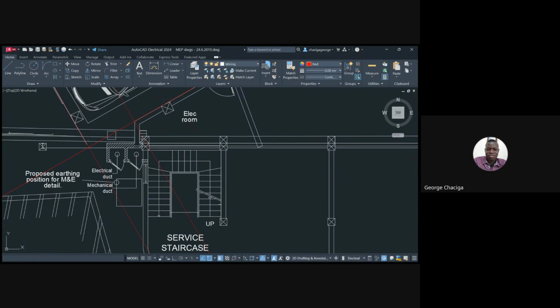Still the spacing is what? We want to achieve a spacing. Our target spacing is 4.5. So we divide by 4.5. Remember, we are working in millimeters, so 4.5 is that in millimeters. When you enter, this gives you 2.9. So you can't go for 2 lighting fixtures, because this is really close to 3 fixtures. So again, you come and select this.